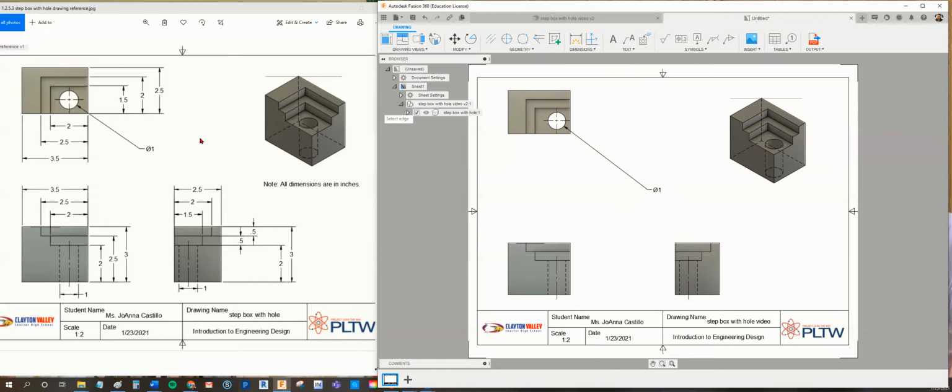So now we're going to do the rest of the dimensioning, which is just corner to corner lines. Click on dimension. I'm going to start with the front view. Remember, it's going to ask first corner, second corner, and make sure you use this green rectangle, this cube. First corner, left click, second corner, and then I'm going to go out pretty far on this one so you guys can see it. Again, this is going to be exaggerated, just so you can see where all the dimensions are.